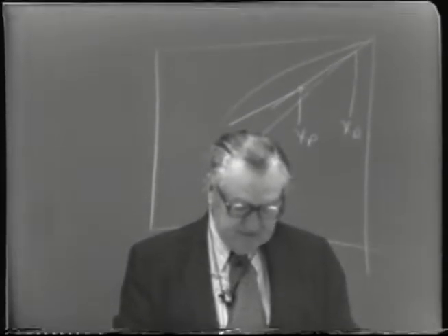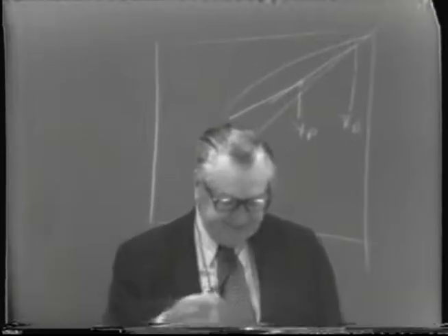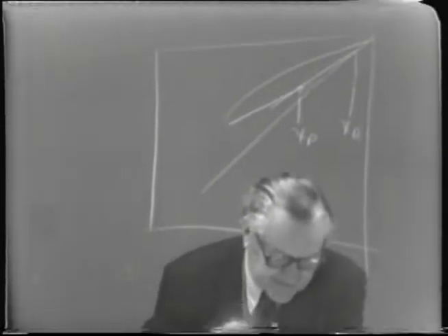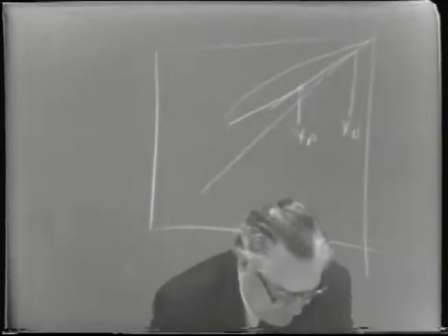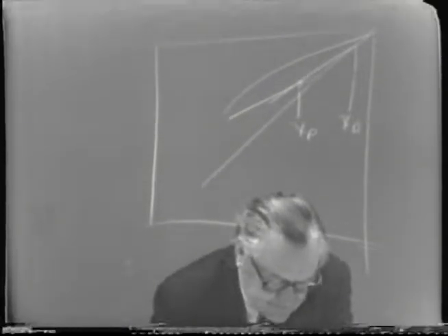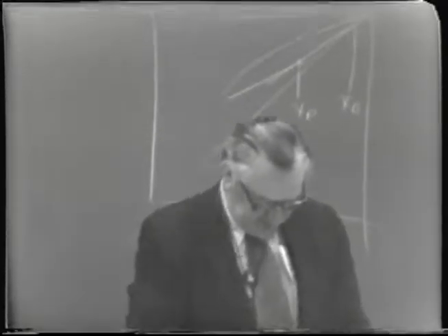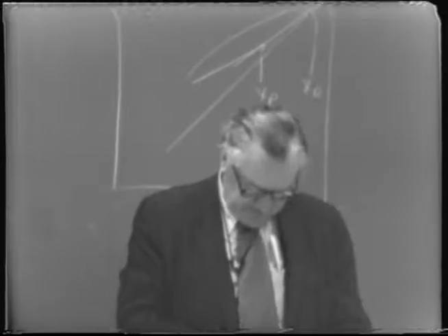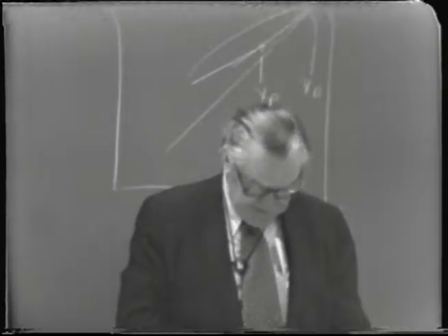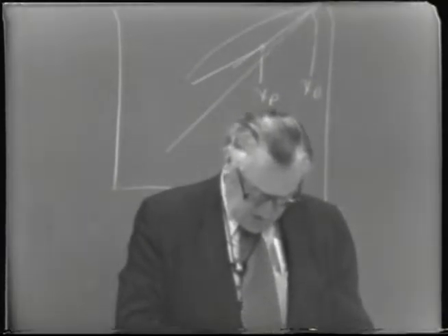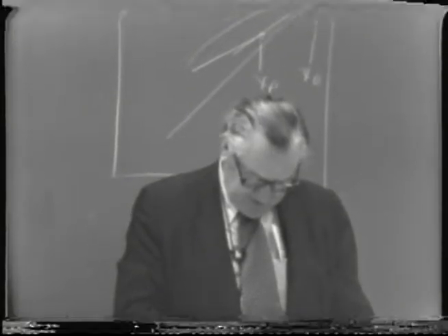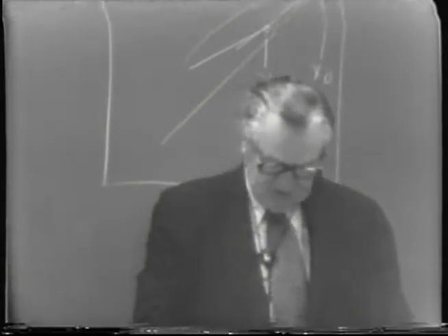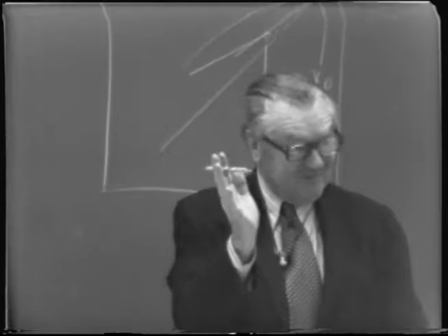So we continue on down, taking our stepwise steps. First of all, we've plotted in the Q line, of course. We can plot X sub F down there in the lower left-hand corner on the main chart. And the slope of the Q line of 15.4 to 1 makes it just slightly inclined to the right from the vertical.